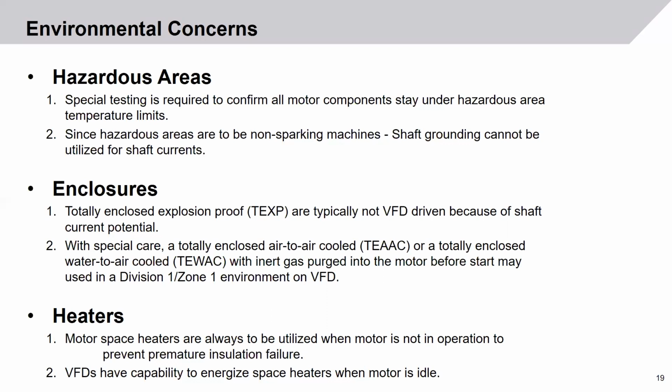Another concern is the space heaters. Space heaters must always be utilized when the motor is not in operation to prevent premature insulation failure. VFDs have the capability to energize space heaters when the motor is idle without having somebody actually go energize the heaters.